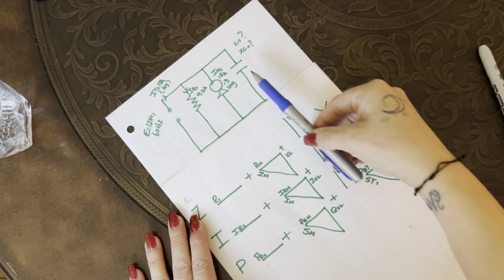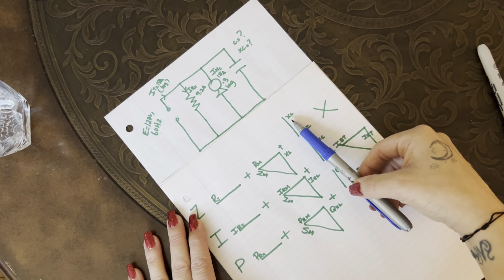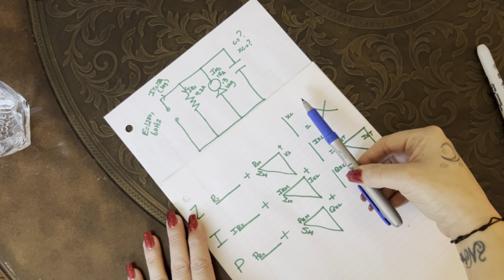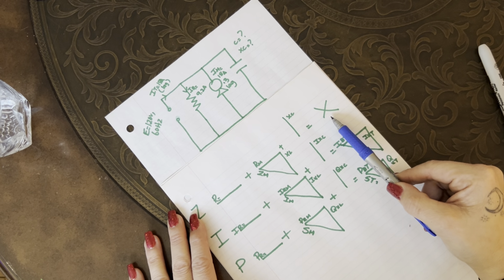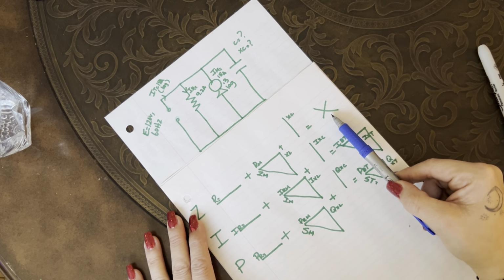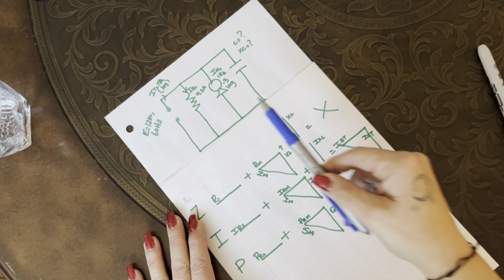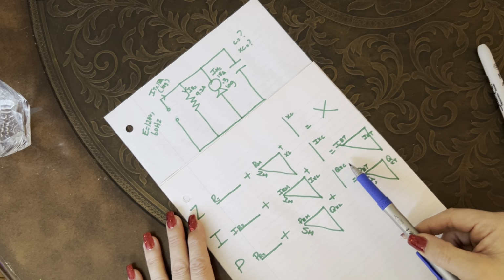And then the capacitor is always pure and it's always drawn in vertical position, 90 degrees out of phase with the XL component. And it's drawn upright again because this is parallel. So you can see that I've X'd out my impedance total triangle because in parallel we cannot use an impedance total triangle. We are limited to only using the impedance for the branches, right? So now I'm going to take this information and populate it into my triangle.